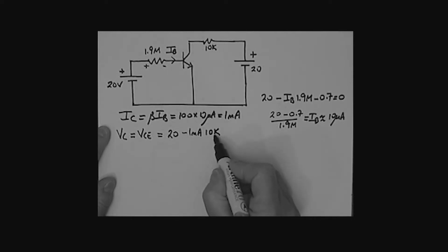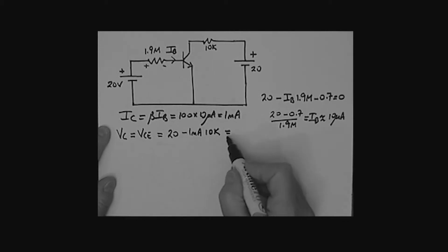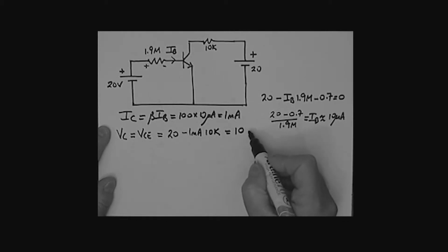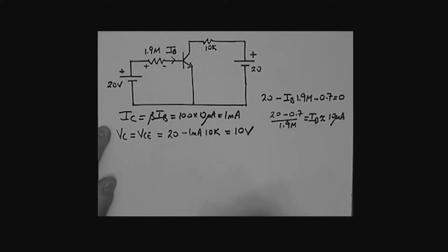That evaluates to 10 volts. And so really it's 20 minus 10, which means that VCE, which is the same in this case as VCEQ, is equal to 10 volts. Okay?